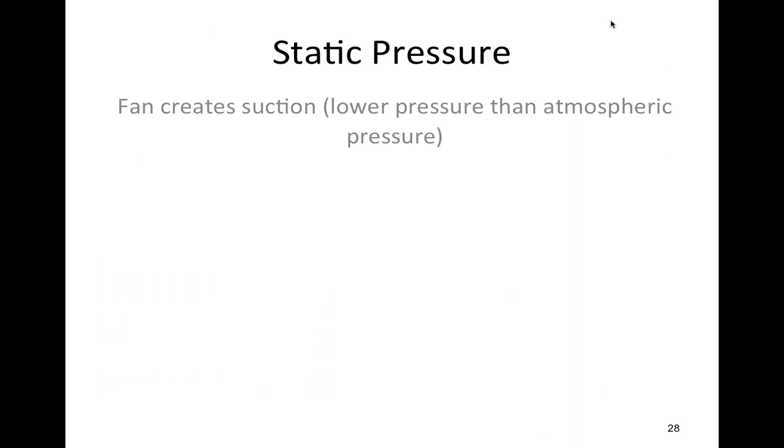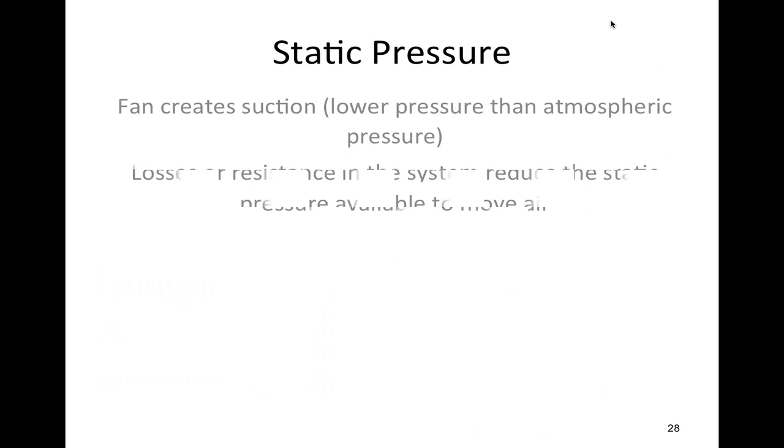Okay, here's some more duct transitions. That's just changes in, say, shape or size. Flexible duct, which is really obnoxious stuff. Blast gate, when we look at our equipment downstairs, that's a kind of a damper, to turn flow on or shut it off. They're not really designed for regulating flow as much as a regular damper, kind of like these things you see axially mounted. But it's really intended for turning on and off, but you can use it to regulate flow as well. It's basically, it blocks a duct or blocks some part of the duct to slow the air movement down. We're going to be using that ourselves.